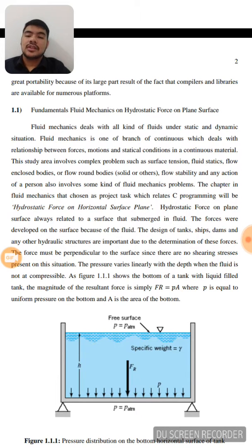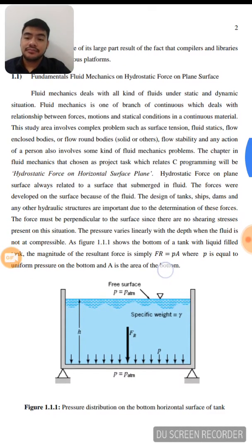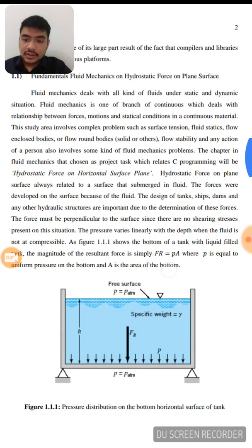Okay, so the chapter chosen in fluid mechanics as our task to relate with C programming is the hydrostatic force on a horizontal surface plane. Basically, hydrostatic force on a plane surface is always related to a surface that is submerged in fluid. Forces are developed on the surface because of the fluid. The design of tanks, ships, dams, and other hydraulic structures is important due to the determination of this force.